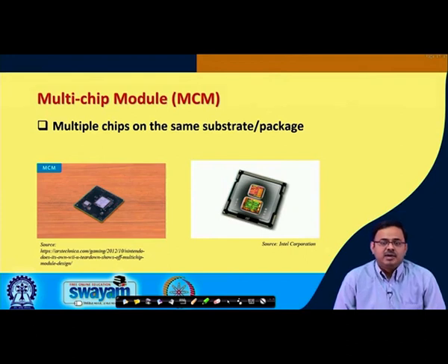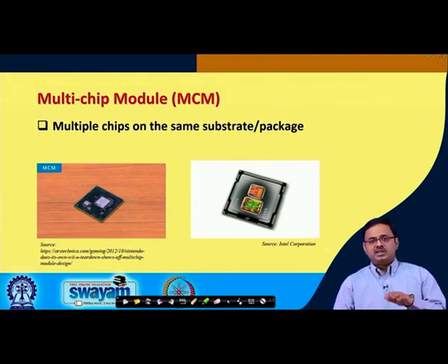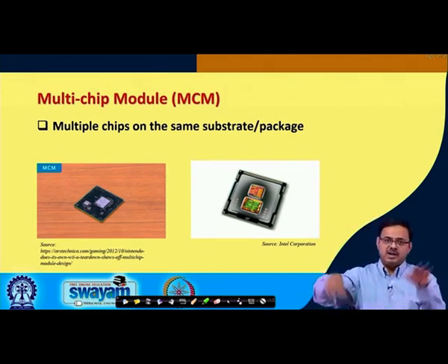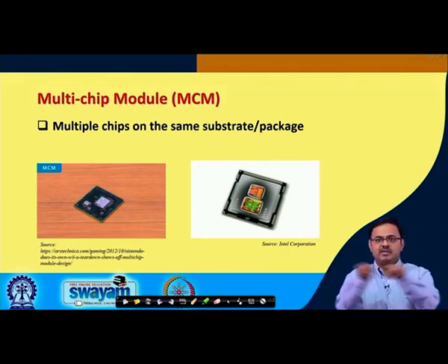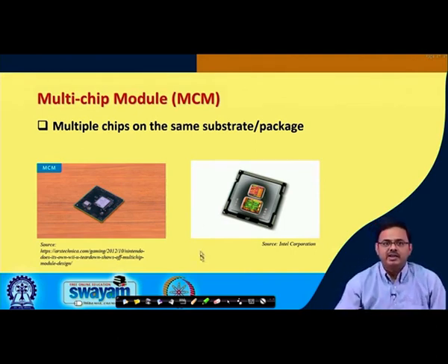But now, instead of having chip 1 to substrate 1 to the motherboard, then substrate 2 to chip 2, with one layer of interconnect at each level or interface, you just have a connection between these two through the wiring traces inside this piece of silicon. Of course, there are two levels of interconnects, but I have definitely gotten rid of two things.